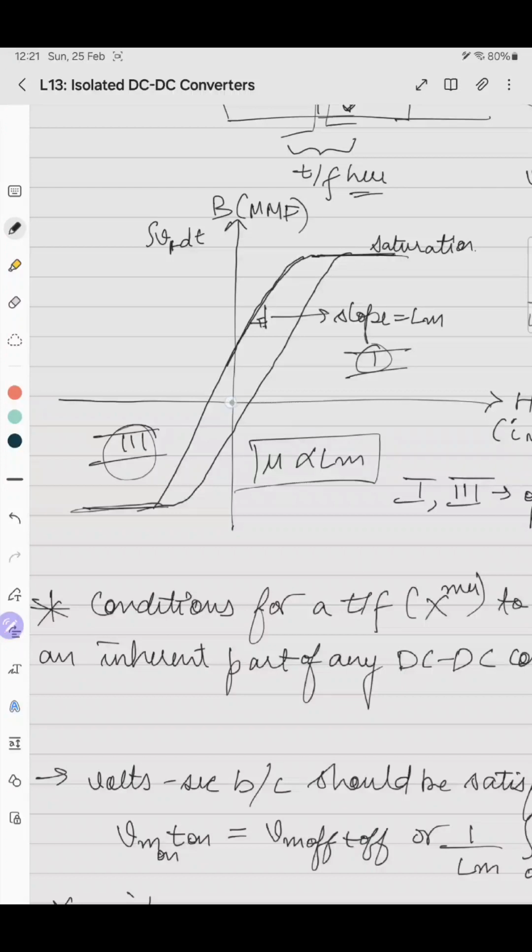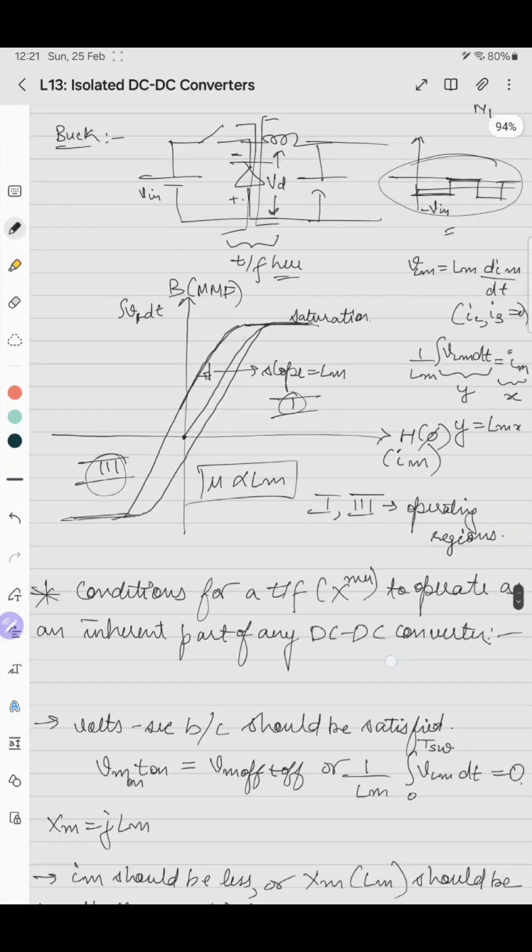So you can say that from zero magnetization or from zero residual flux, it starts magnetizing. Then if you increase the H or IM in the negative direction, or if you try to demagnetize the core, the B falls and then it goes in this fashion. Then again it increases and increases. So this happens multiple times.